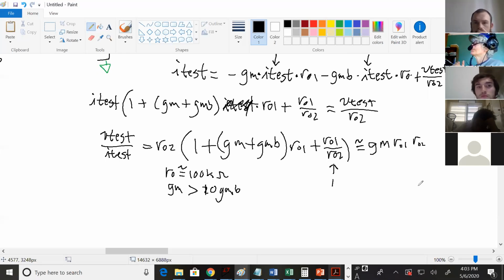It looked like a resistor of size RO. This one looks like a resistor of size RO squared. You'd think if you stack 2 transistors, it would be resistors in series and you'd get 2 RO, but the ROs actually multiply and give you perceived resistance of like 1,000,000 just by putting 2 transistors on top of each other.